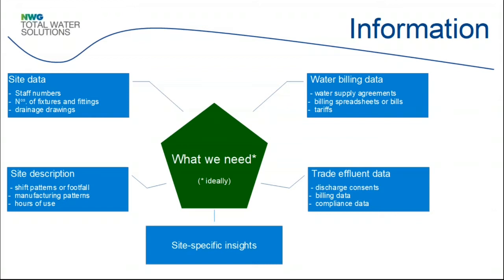When it comes to things like surface water or rainfall capture, we can use Google Earth actually to estimate surface areas. Just before Christmas, I did an audit at a place in Newcastle upon Tyne, and I compared the measurements from a scale drawing done in AutoCAD with some measurements that I took from the same site in Google Earth, and they were actually very, very comparable.